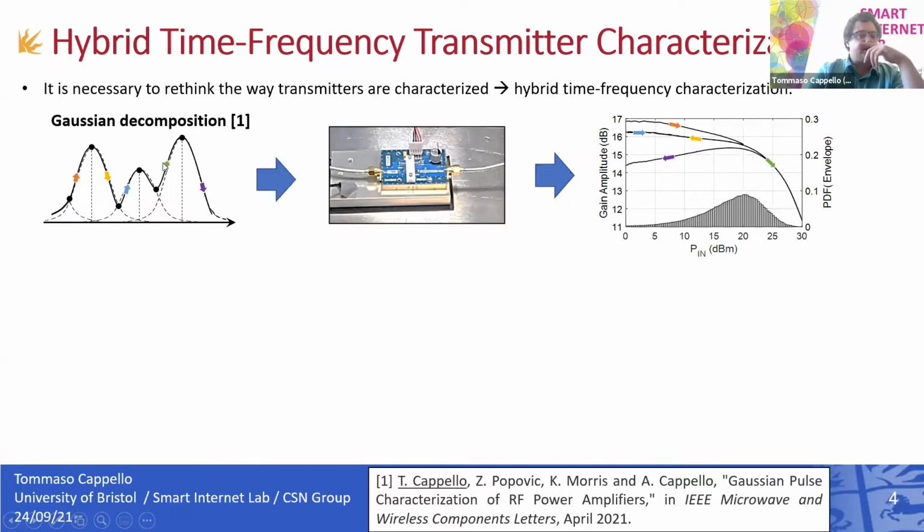As we can see here, these approximate the envelope of a signal quite well, but the capability added is the way we extract the nonlinear memory effects of a power amplifier. For example, if we follow the red arrow here, the gain characteristics of the PA will follow more or less this contour. Then when the signal goes down, the gain drops around 16. Here it is shown as a line, but in reality, what you see experimentally is more like a scatter plot, like dispersion points in the back-off region. These are known as memory effects.